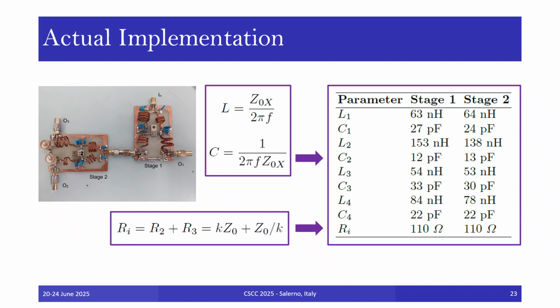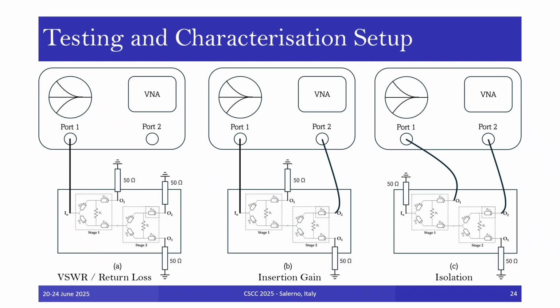The design was implemented on a high-performance FR4 double-sided printed circuit board with a high glass transition temperature, low coefficient of thermal expansion substrate, featuring a relative permittivity of 4.58 and a loss tangent of around 0.02. The ground plane areas underneath the designed inductors were etched away to limit any coupling effects.